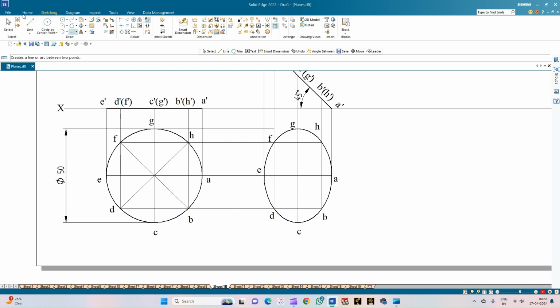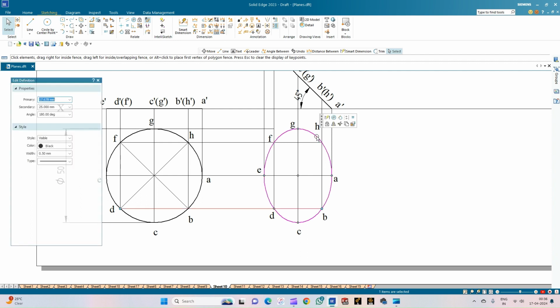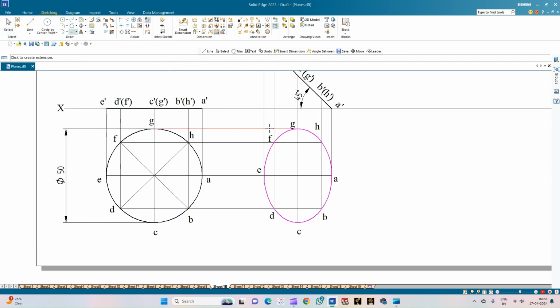Okay. So now we shall select the circle. So here, okay. So keeping the control key, select the ellipse and then the annotations, and also this inner rectangle. So you can just see that all this is getting selected as a single entity.